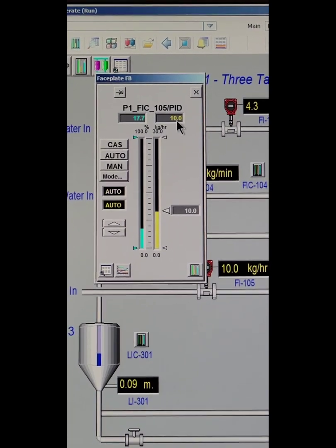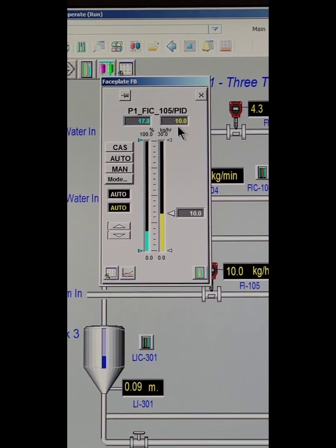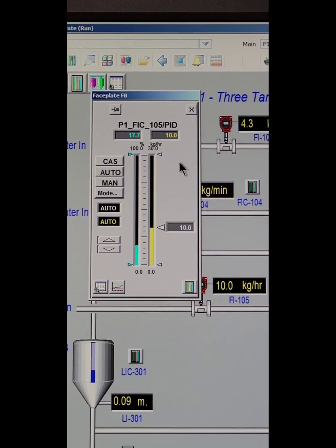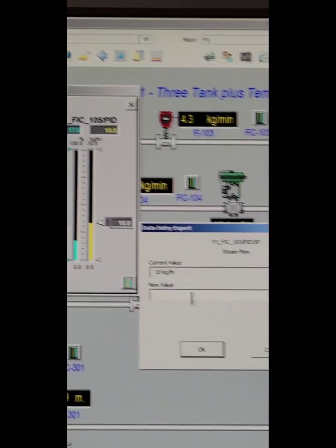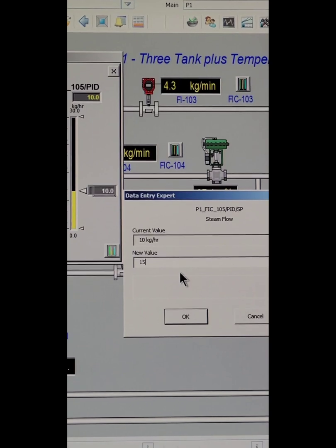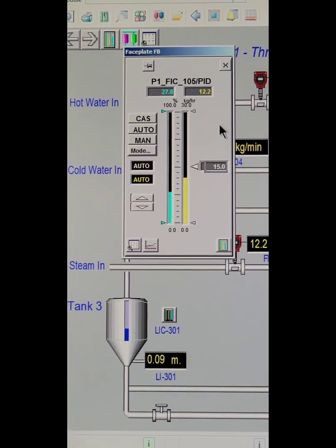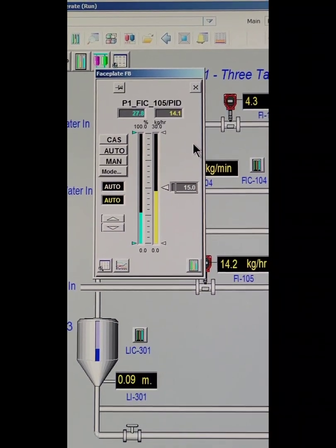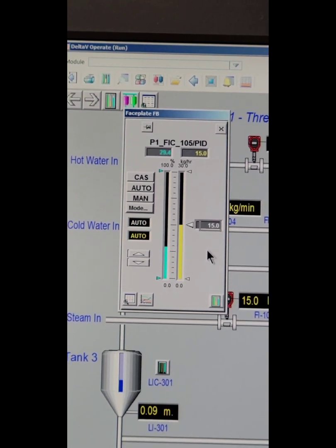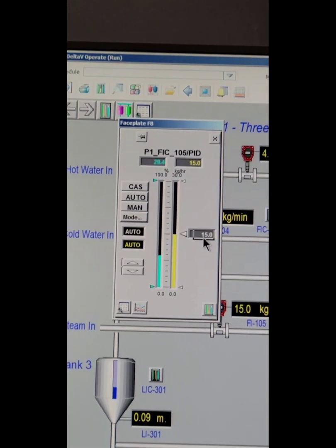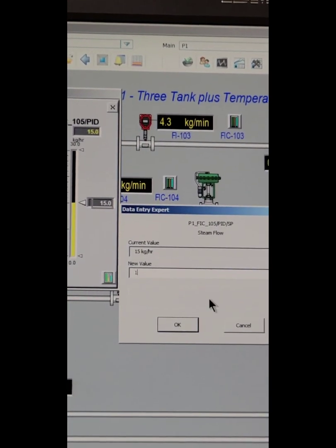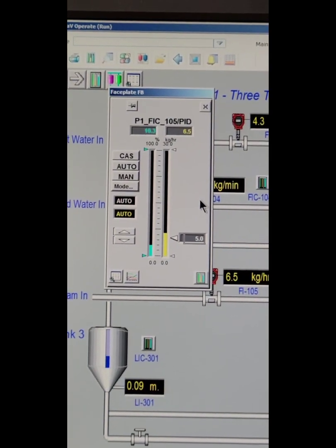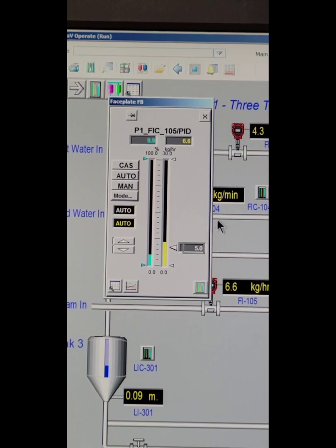So once the system reaches the newest steady state 10, we repeat the previous procedure for the step changes given in table 2. So as a first step, we should increase by 5. So I increase from 10 to 15, and I should wait for reaching the steady state now. In the next step, we should decrease the set point by 10. So from 15 we go to 5, and again wait for reaching the set point.